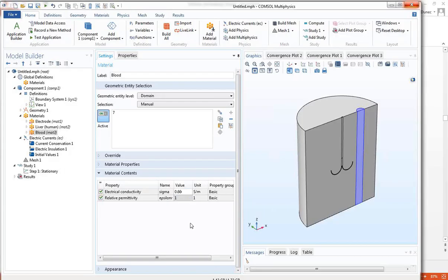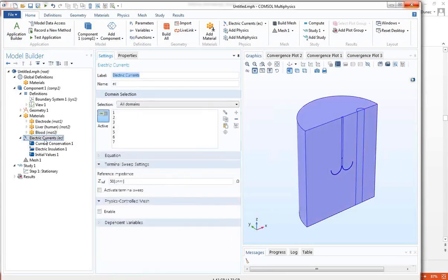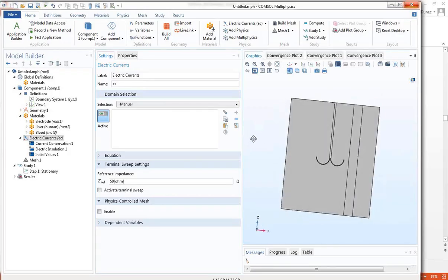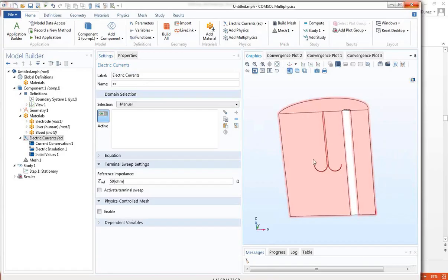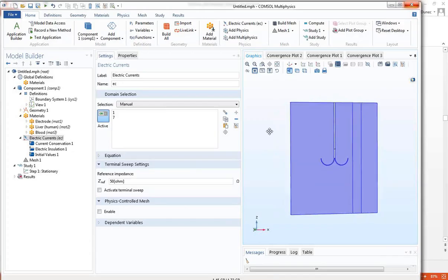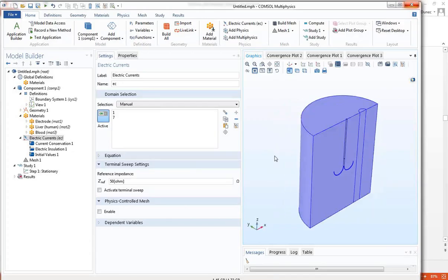So let's go ahead and define where I'm calculating the electrical properties. Meaning, where am I solving the electrical equations? Right now it says I'm solving everywhere. Now, I actually don't need to do that. I'm going to clear this out. I know what the electrical results are going to be in the electrode. This is insulated, and this is where my voltage is. So I'm just going to calculate only in the artery and in the liver tissue. That was that easy. And so now it is not calculating anything in the actual cathode or electrode.